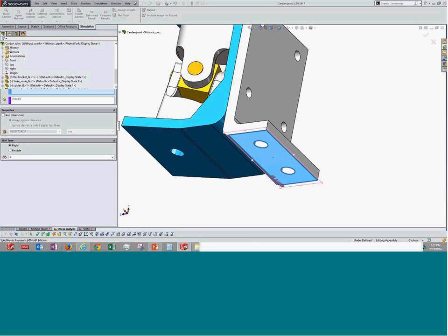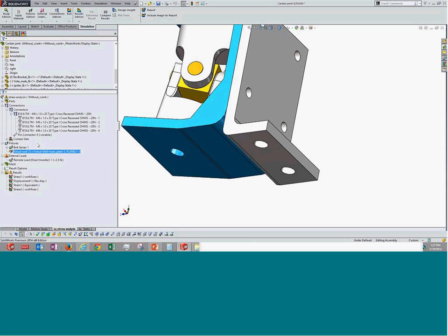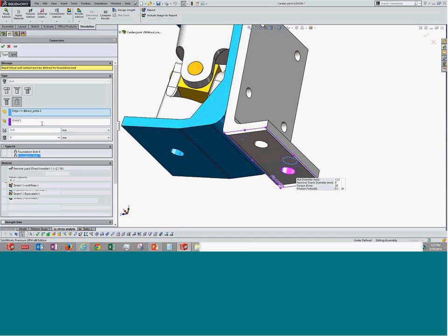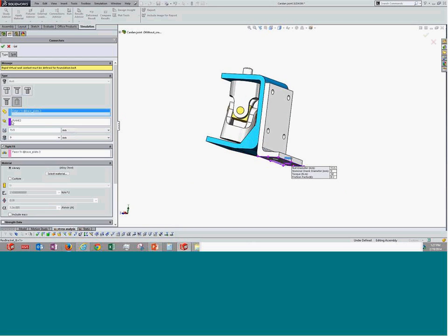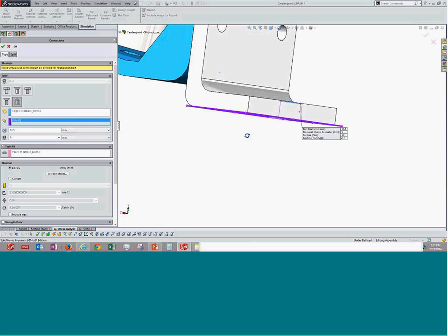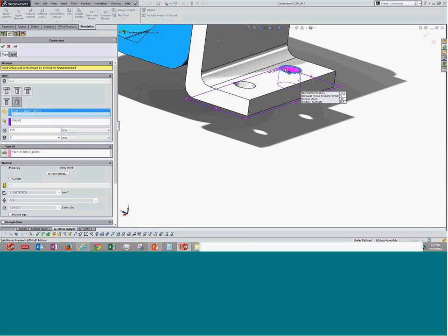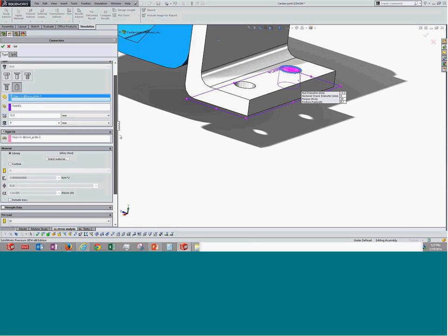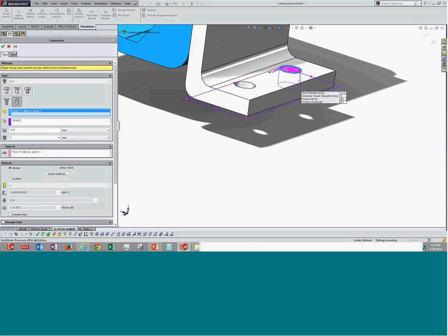Again, if you go to fixtures, we have something called bolt fixtures over there. If you had observed yesterday, we used something called foundation bolt. Those have been used to connect the place that is getting connected to the plane over here. So what we are defining, you can see here, is the virtual wall plane and the top edge of the plate. That's it. The rest of the things remain the same. This is one of the restraints: the common virtual wall and foundation bolts.